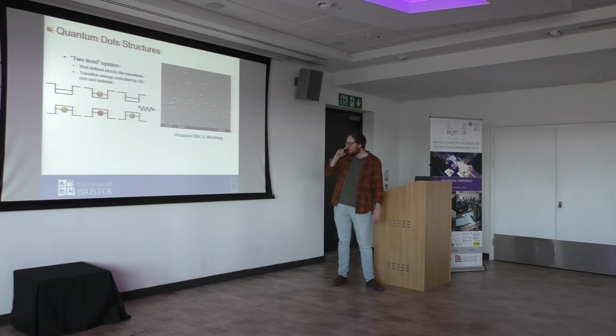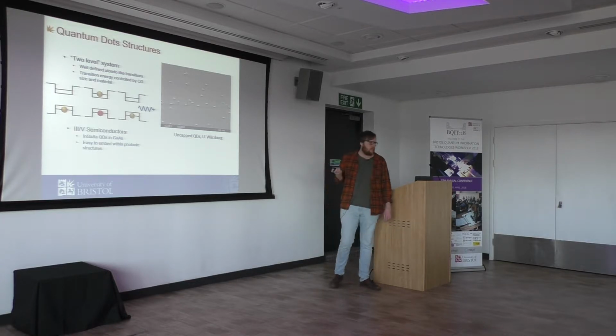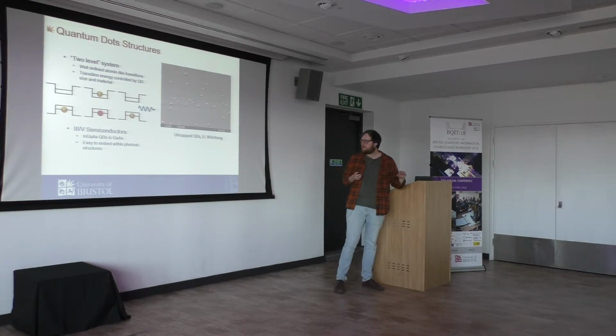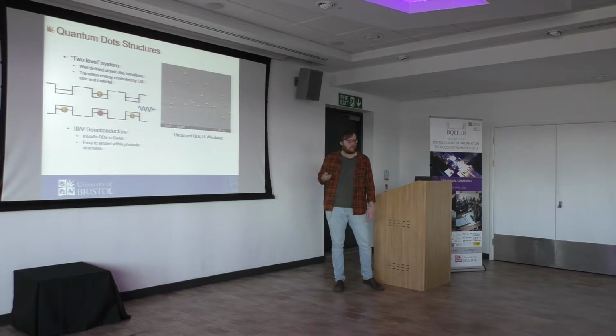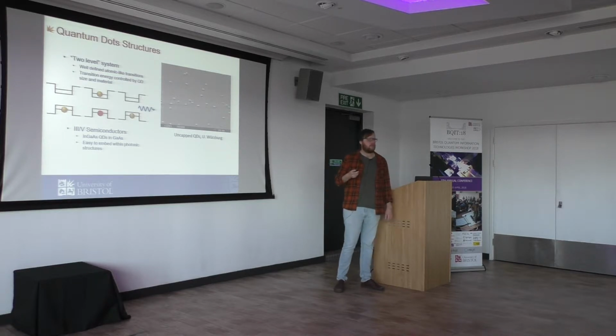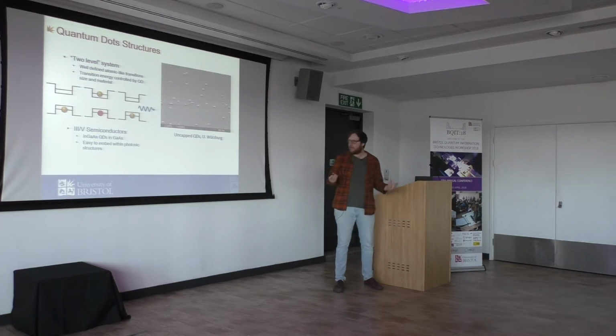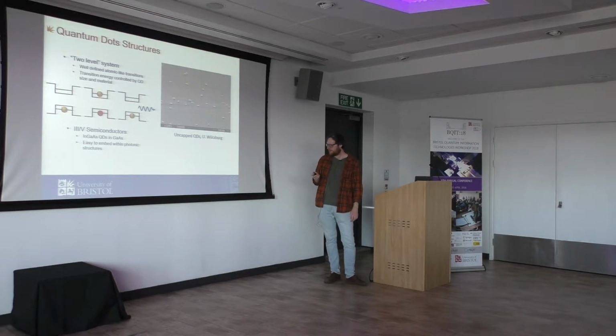technologies. Particularly in these III-V semiconductor systems, where the photonics engineering, as we've seen in the various talks previously, is already fairly advanced. So we can embed these quantum dots into really high quality photonic structures. And that's absolutely key if we want to be able to input and collect single photons from these devices with any sort of efficiency, and we want to scale things to larger photon numbers.